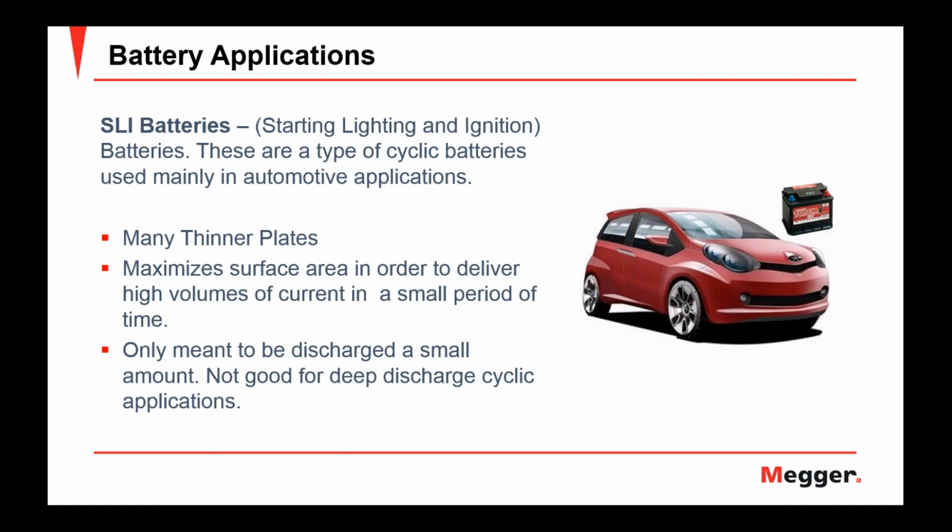These are specifically designed to supply high levels of current for very small periods of time, and they need to be recharged right away. They're not meant for deep discharge. This is why cars have alternators in them. As soon as they're started, the alternator has to recharge that battery. And as we get into failure modes, you'll see why.